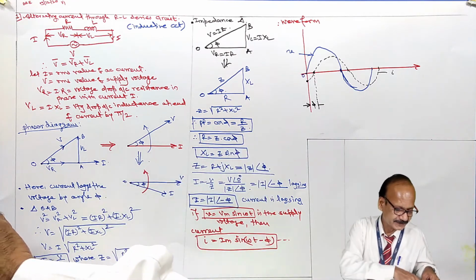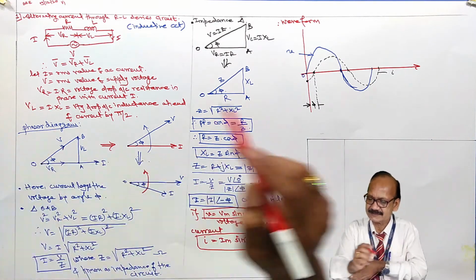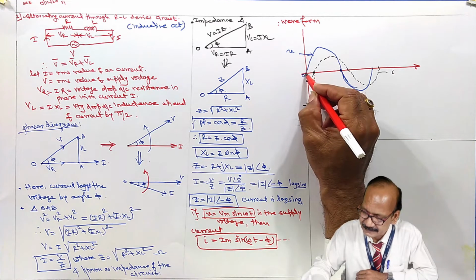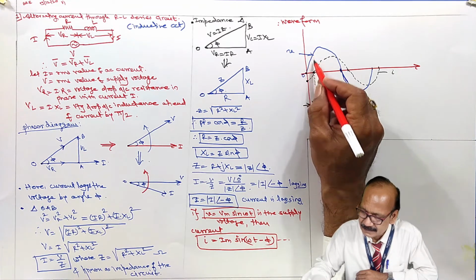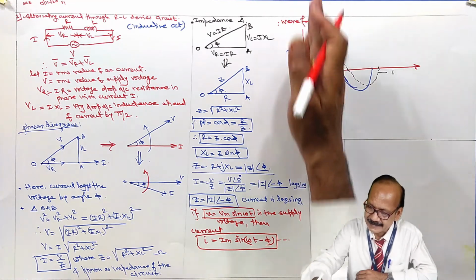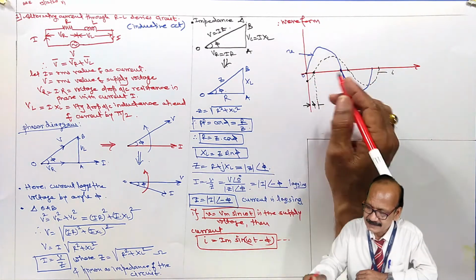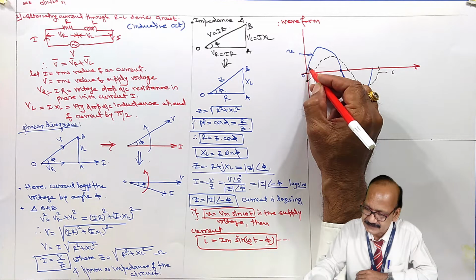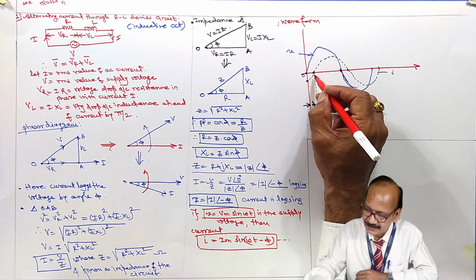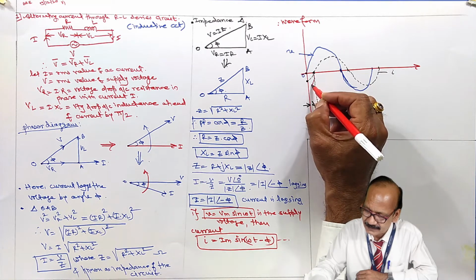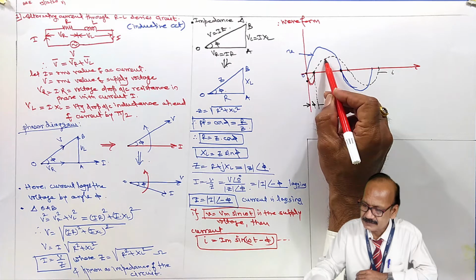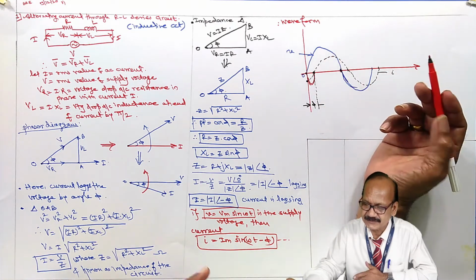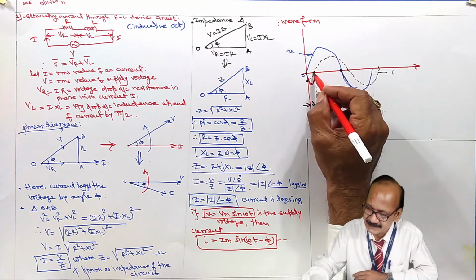Now the power expression we can draw from this. See, in between this and this, if you draw the line here, in this band current is negative, voltage is positive, and the magnitude is small, and therefore the resultant is small. Now in this band, both current and voltage are positive, their product is positive, and their magnitude is also large.